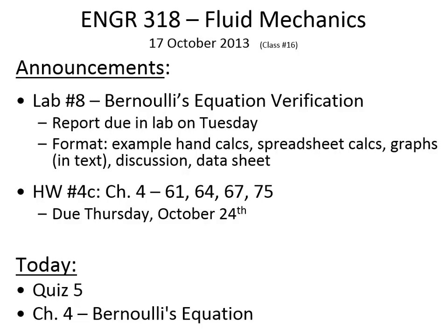Okay, so in that video we just watched, it was showing what can happen in a pipe network that maybe a designer wouldn't ordinarily consider. There are going to be unexpected things like air pockets traveling through the system. When a large wave of water going through the pipe network traps a pocket of air, that air comes out and drenches people and throws 1,000-pound manhole covers straight up in the air and lands on vehicles.